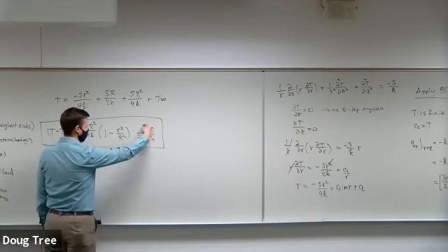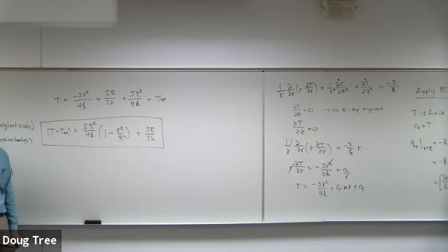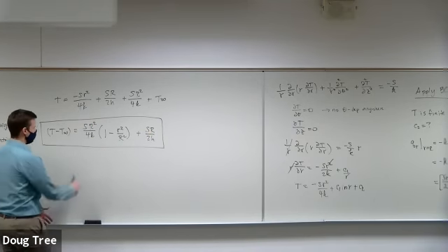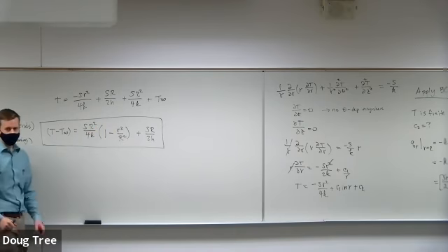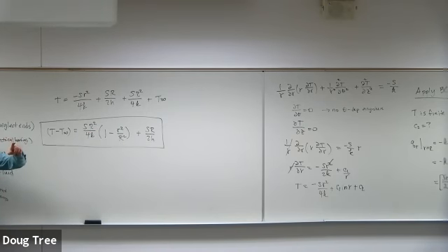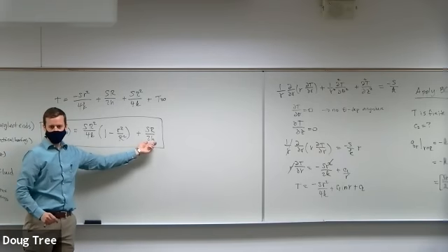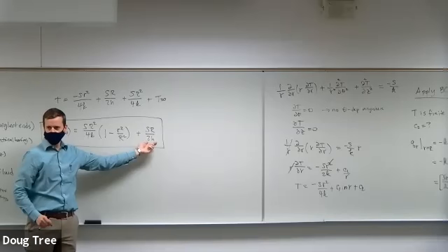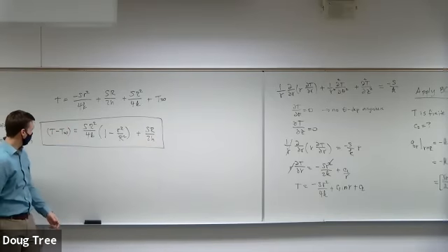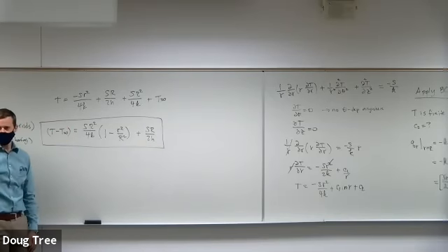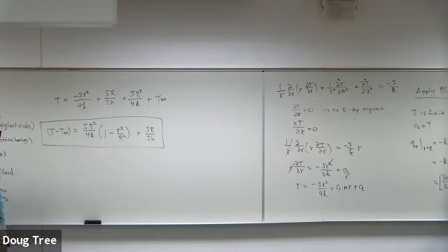this constant generation of heat coming from my source term, right? And then I've got this parabolic profile. So I've got this temperature distribution that's parabolic, and that's how much it is above T infinity, the outside piece. So at steady state, it's heating internally. I get this parabolic profile that's shifted up by some ratio between the source term and the heat transfer coefficient. Okay, and then I've got T infinity outside.